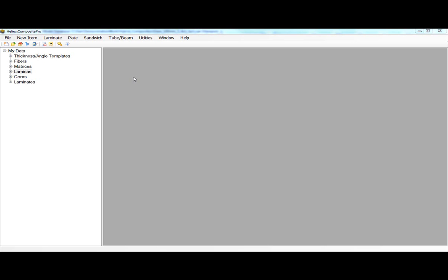This video will demonstrate how to conduct a progressive failure analysis of a composite laminate using HeliusCompositePro. A progressive failure analysis looks at each individual ply in a composite laminate, and when that individual ply fails due to a composite failure criteria, that individual ply's mechanical properties will be degraded to a fraction of the pristine stiffness.